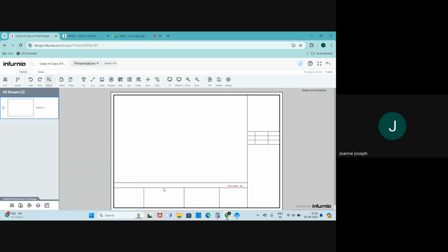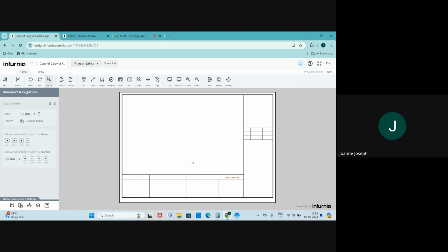One thing to bear in mind is that since this is a section line, these lines would not be visible after this particular line. So in this gap, I'll just try changing the layers. If I click on this and bring it towards the front, that's not working. So it'll be better to create another line here and then delete the section line. So I click on remove section line. Now you can see that these lines are visible. So you can always delete section lines later on.